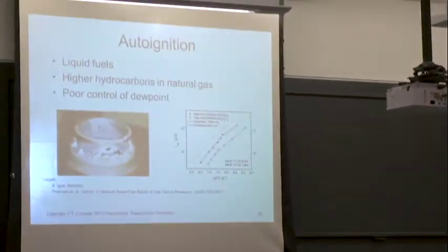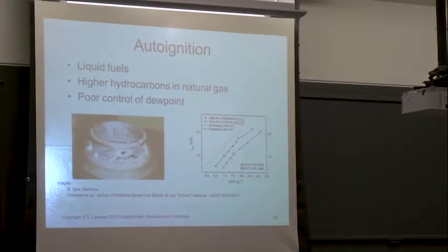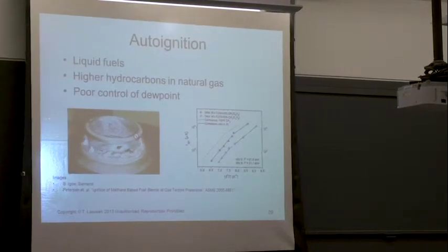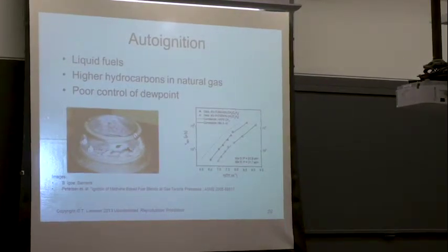When they talk about poorly controlled dew point, what they mean is that you really have to spend a lot of time designing your whole fuel metering system and modeling all those non-ideal gas effects to make sure that you don't get liquid dropout in your fuel.